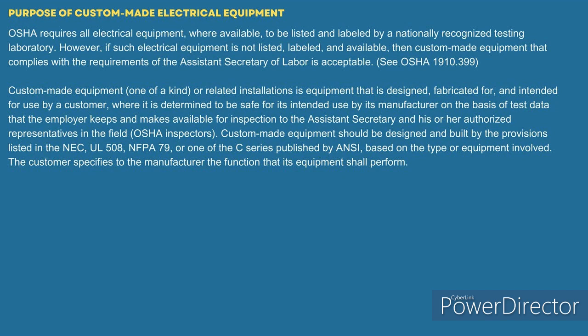Let me ask you this. Let's say you go outside and you have equipment out there in a hazardous location, and by listening to the golden boy Ryan, he says the end of the wiring method is where your outlet is. So if I go out there in a hazardous location, you're going to tell me I need GFCI protection there, even though it's custom made equipment and they determined it doesn't need it? That is not correct. I don't care. It is not correct.